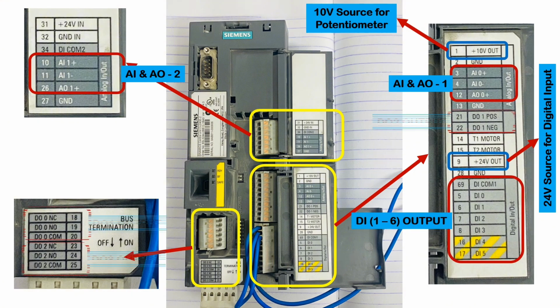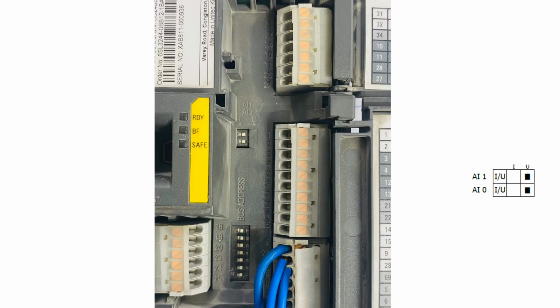You can see at both the left and middle of the right terminals are the digital outputs. On the left there are two relay outputs. You can use NO-NC contact from this relay. Let's learn some important factors.